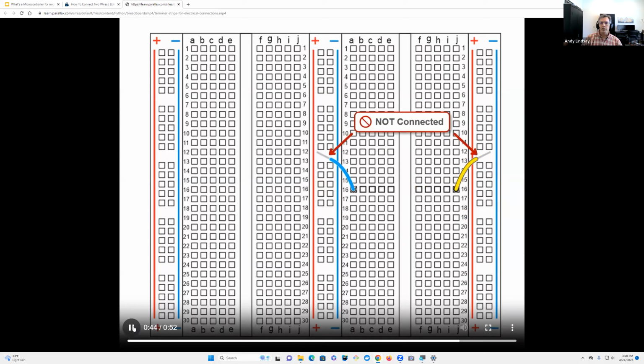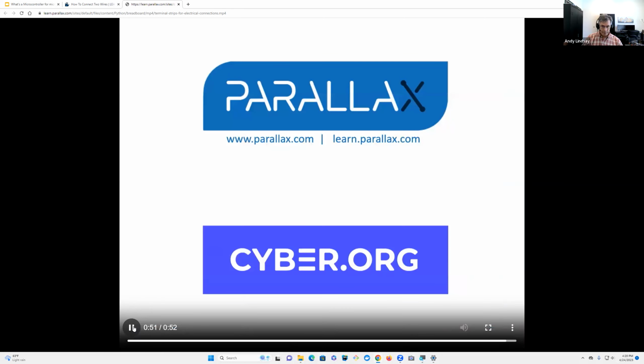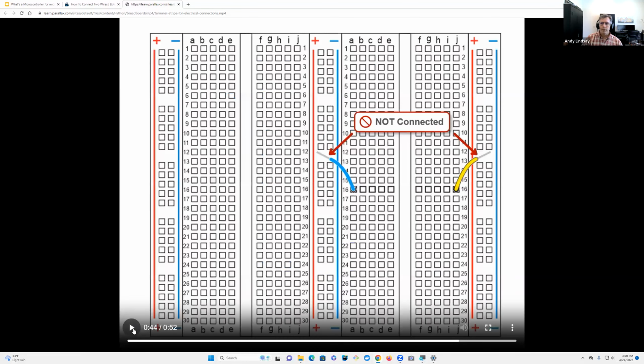And then also that you can use a jumper wire to extend a row of 5 to basically make it a row of 8. So if you add a jumper wire to connect 2 rows of 5 electrically, then you have 8 sockets left. So you could connect up to 8 things. And of course, you can expand that further as needed.